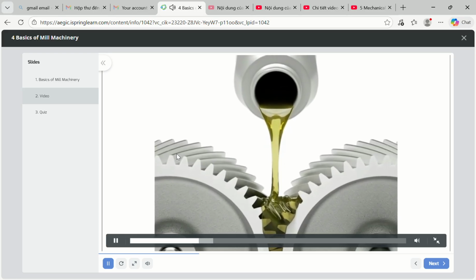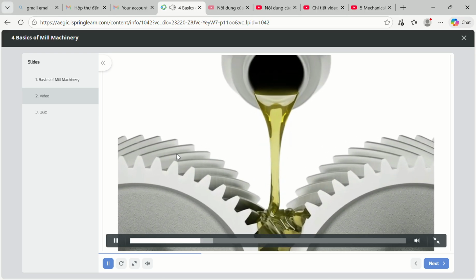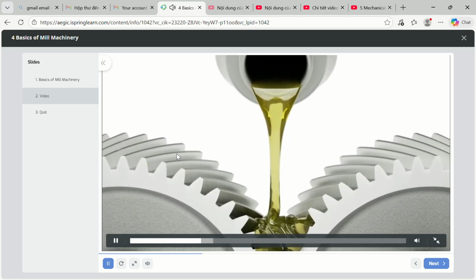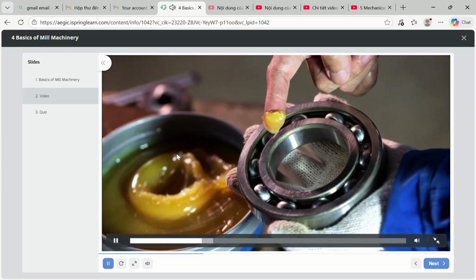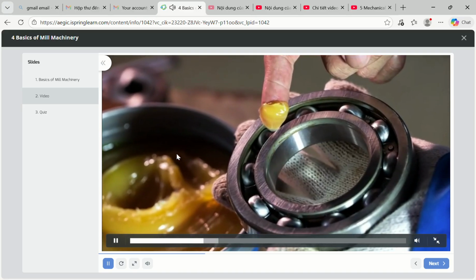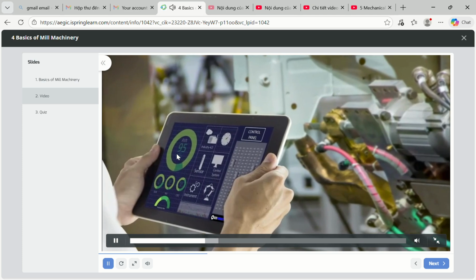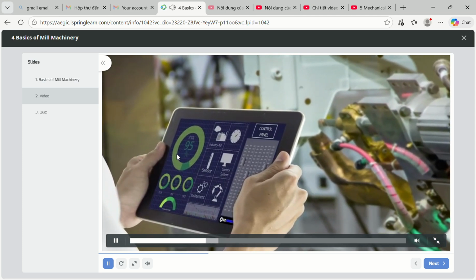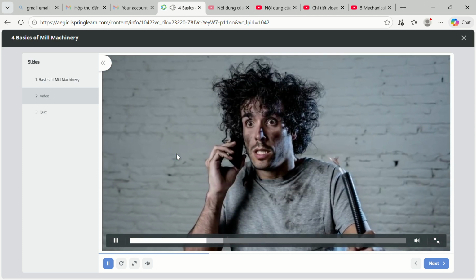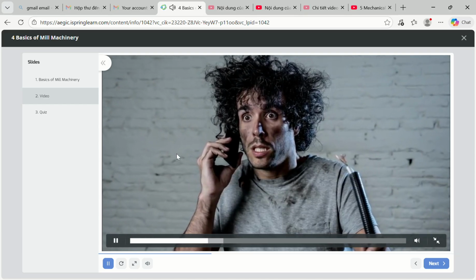All pulleys, chains and gears should be properly lubricated and maintained as required, along with all bearings and other moving machine parts. It is more efficient to carry out preventative maintenance on equipment, rather than allowing it to break down at an unplanned time, resulting in operational problems.